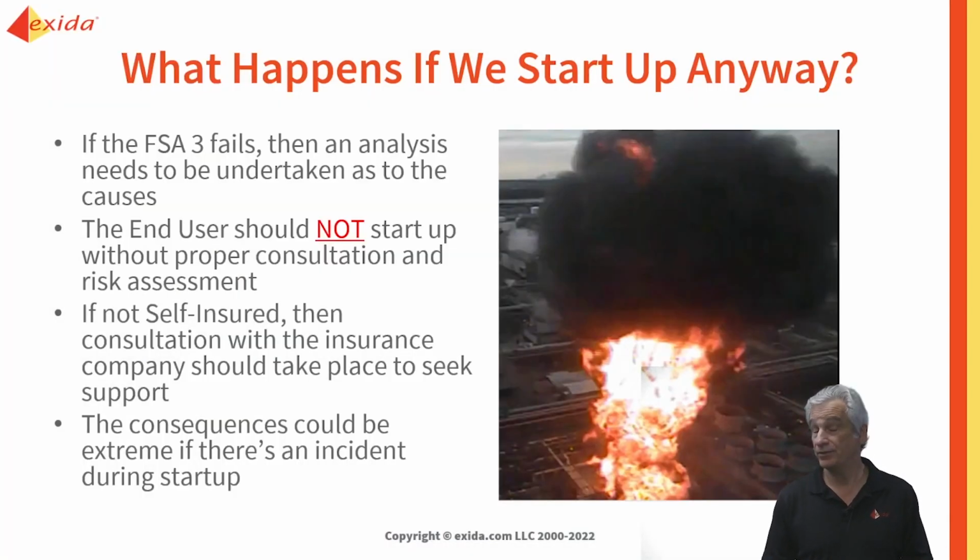What happens if the end user chooses to start up? There's nothing stopping the end user starting up, but the point there is that the end user is now accepting considerable risk. Plus, if they're not self-insured, they better check with the insurance company to make sure that the insurance company will support them. Because remember, statistically, most accidents occur during startup or maintenance activities. So if we failed our FSA 3, we really shouldn't be starting up because we're accepting a significant amount of potential risk. And the consequences could be extreme.